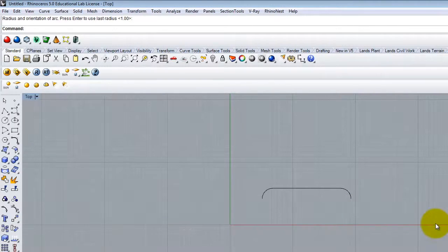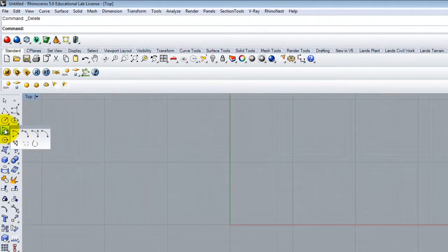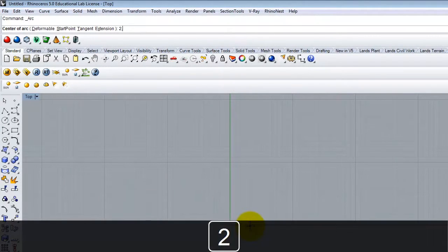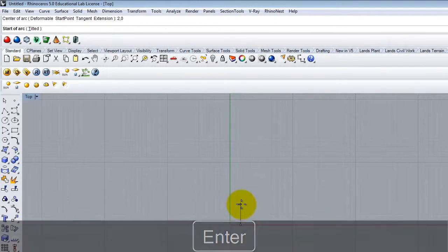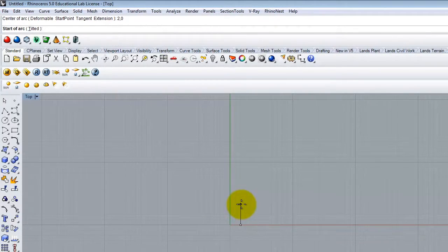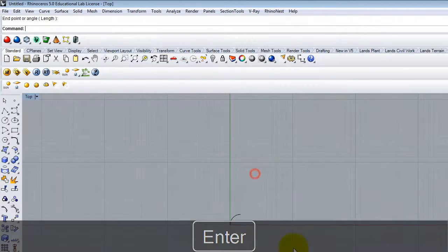So there's a lot of different ways of creating this. If I started with the arc, again, I can choose any one of these as my option. Let's say I did the center, the start, and the angle. If I did that, my initial coordinate would be 2 over, so it would be 2, comma, 0 to start. And I didn't use the @ sign because it's not relative to anything. It's relative to the absolute plane. And so we could do 2 inches here, and then we could go right there to create the first one.